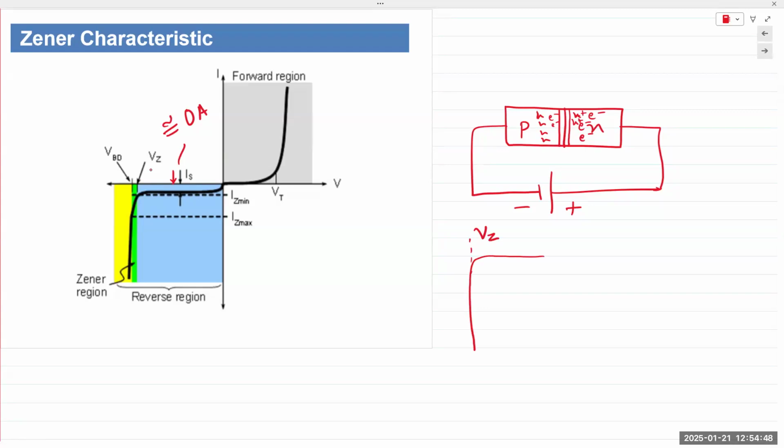There's a second effect that takes place in reverse bias, and that is avalanche effect due to impact ionization. It's because when you're applying a voltage, the electrical energy is transferred to the carriers. The holes and electrons that are moving through will start moving randomly through the circuit. And because of the heavy doping, there's a large number of these charge carriers present.